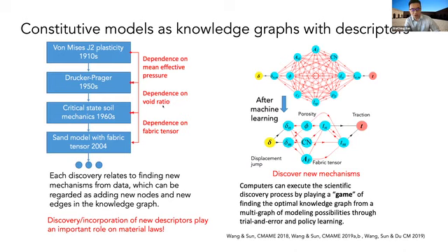For critical state soil mechanics in geomechanics, we introduced the dependence on the void ratio and overconsolidation ratio in the hardening rules. And in recent work, we introduced the fabric tensor to introduce evolving anisotropy. What we can think about this history is that one of the major roles is the introduction of new descriptors that can help us define the material and yet are measurable.